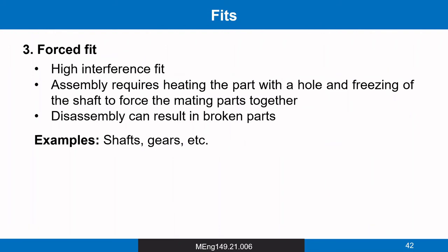And the forced fit. This is the high interference fit. This requires heating the part with a hole and freezing of the shaft to force the mating parts together, and disassembly can result in broken parts. Okay, so sa driving fit is nag-involve siya og heating. The press fit is that cold pressing siya. So cold pressing, wala involvement of heat.